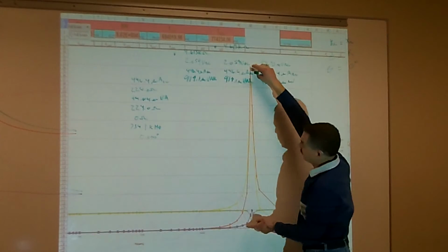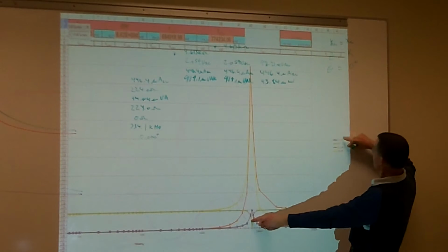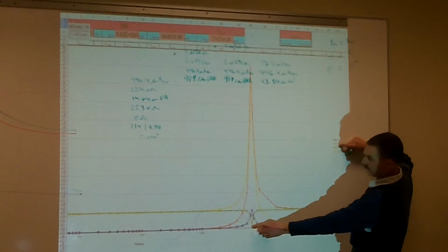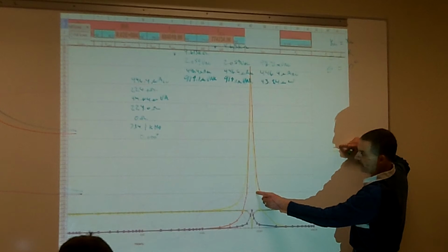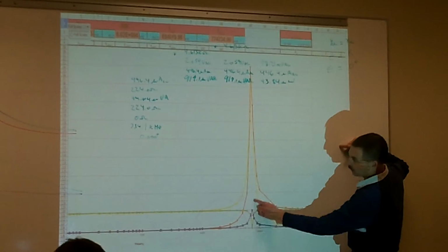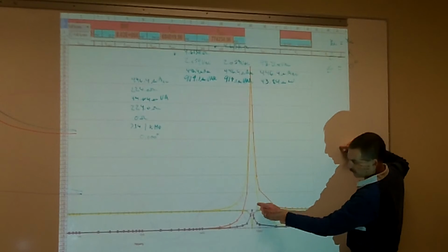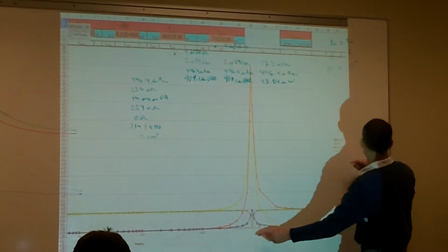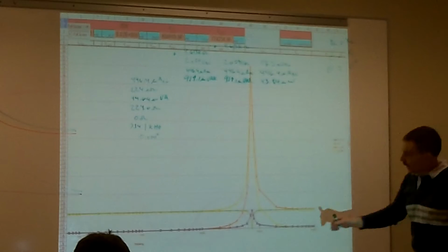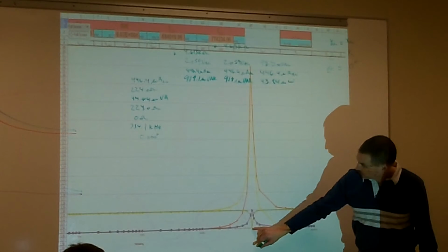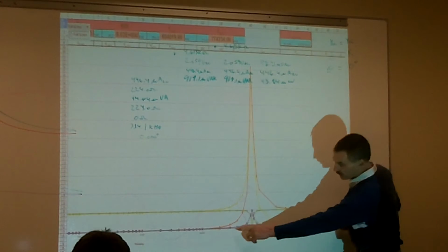So right at this point, where this thing gets to be a really high peak and the voltage gets really high, if I'm looking at my green one here, this is the sum of my two voltages, the voltage of my capacitor and the voltage of my inductor. Right when those two peak out and I algebraically add them up, you can see that green line spike down to 0 volts. That's right where I hit my angle of 0 degrees. Those two voltages ended up canceling out across the inductor and the capacitor, and the only thing that it leaves then is the voltage across the resistor.